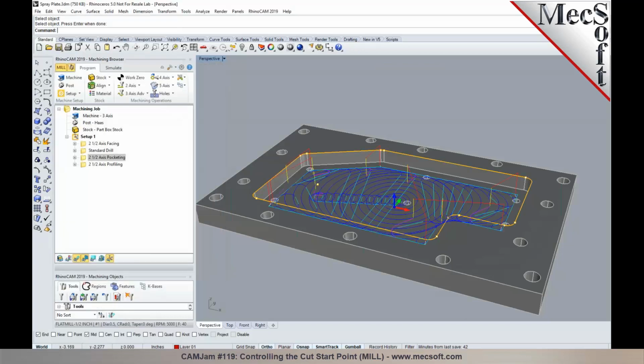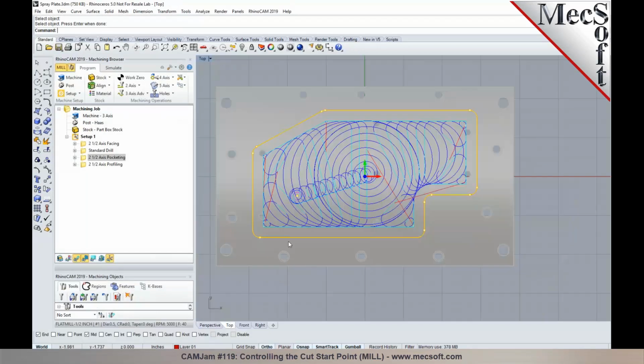And then as you generate your toolpath, you will notice that the cutter plunges in and creates your ramp motion at the start point, and it creates this high-speed cut pattern from the start point to the widest area where it starts creating your spiral path. In pocketing, this also applies in other operations like 2-axis roughing and 3-axis horizontal roughing. You can control the start point where you can have a pre-drilled hole, and then you can use the location of the pre-drilled hole for where you want the cutter to enter.